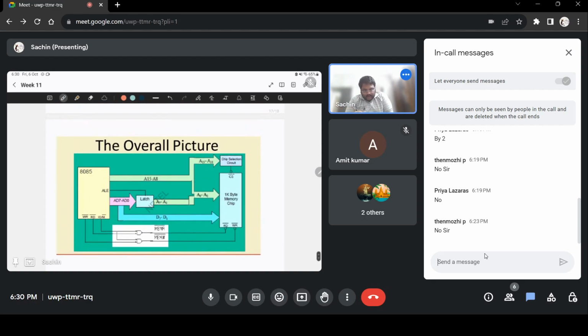That is if you have multiple chips. But here they have given only one memory chip, right? So it's a bit different here. If you have only one memory chip like this, then they'll use these bits to determine whether this single chip is being accessed, right?